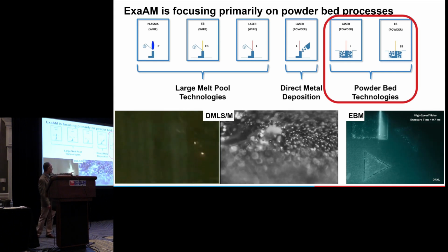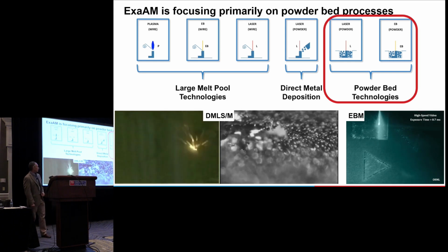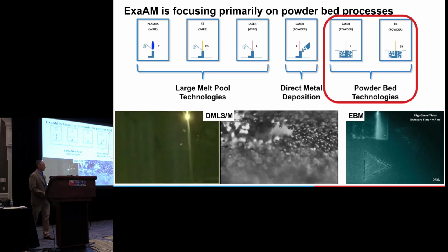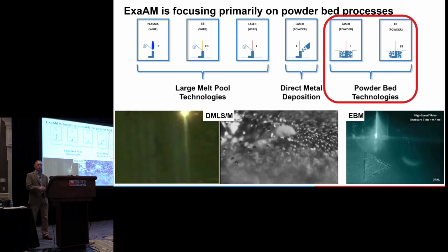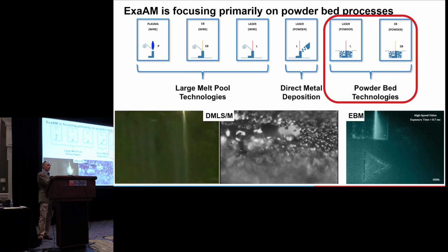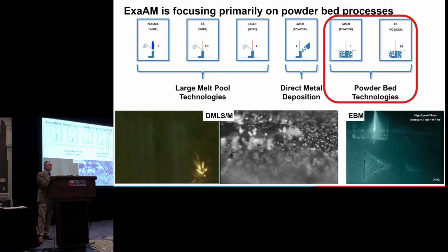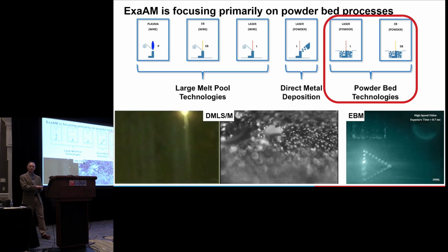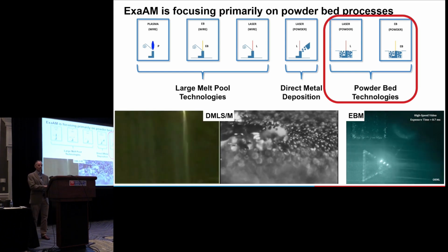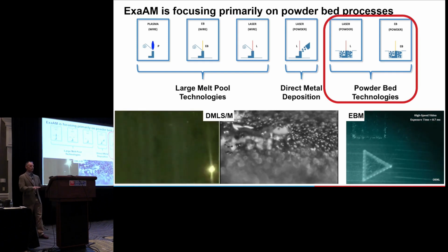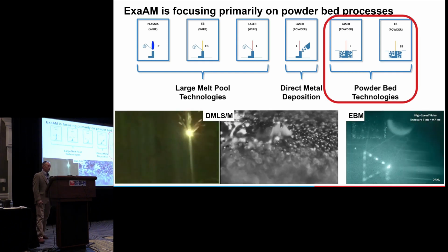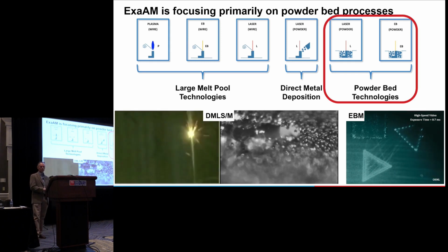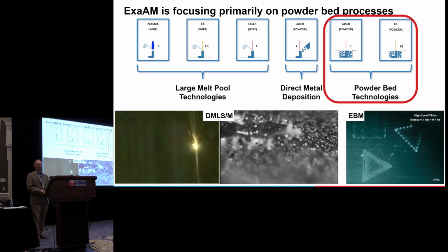On the right, you have the e-beam process, and one of the things you can see is the spatter is less. You have a sintering stage that happens that kind of locks the powder in place, and with an e-beam, you can move the beam much more rapidly than you can with the laser. There are pros and cons of each technology, and certain features that are better with one or the other. Surface finish differs and things like that.